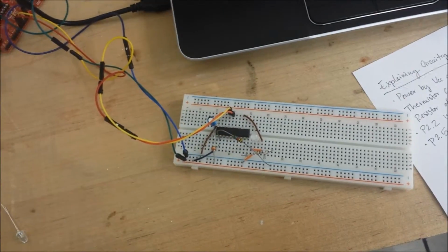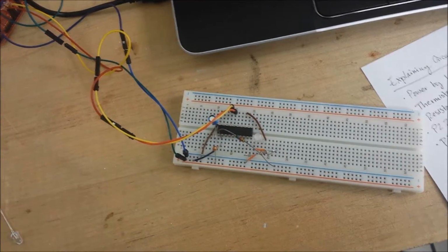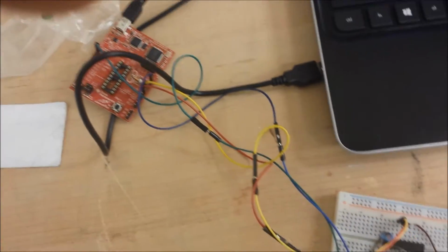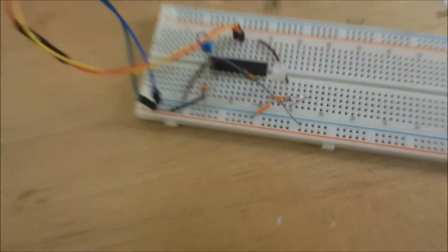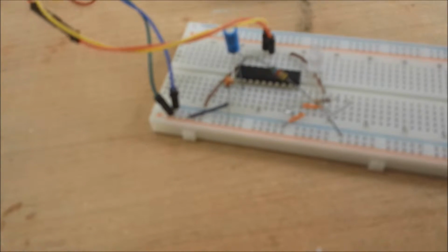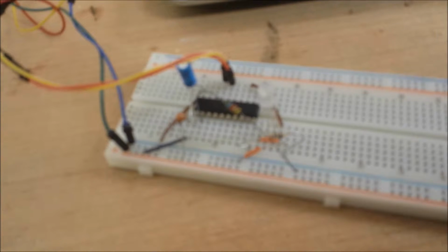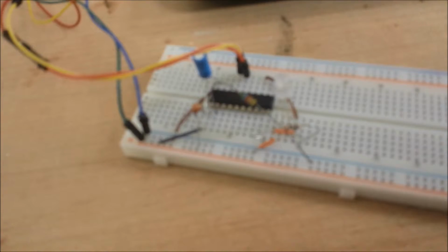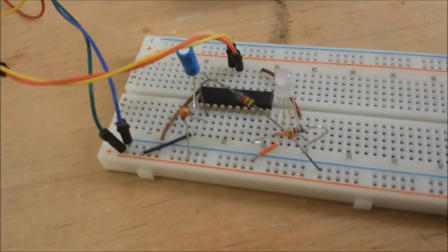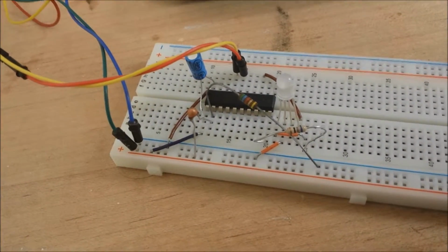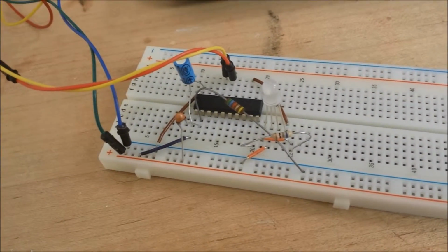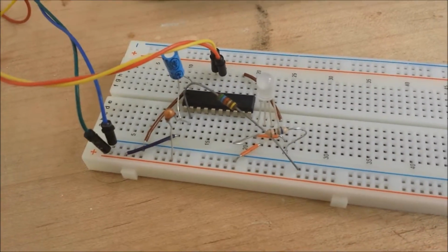The actual circuit implementation of the mood ring. First, we have a VCC and a ground wire powering the breadboard. Pin 1.0 of the breadboard is connected to the VCC by a thermistor. That same pin is also connected to ground by a resistor of similar resistance value to the thermistor. Therefore, pin 1.0 will feel a voltage depending on the value of the thermistor, which will change according to the temperature that the thermistor feels.